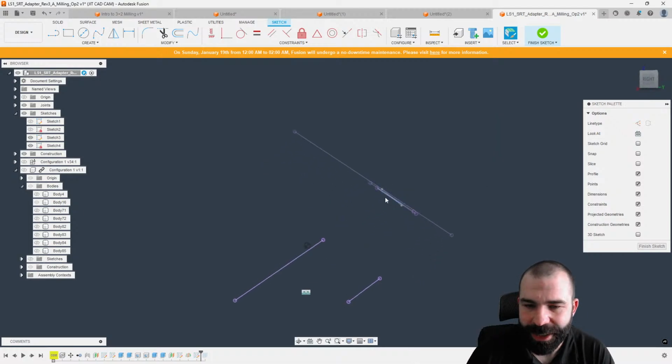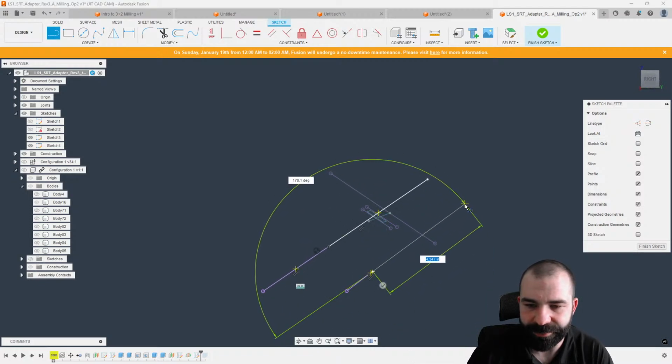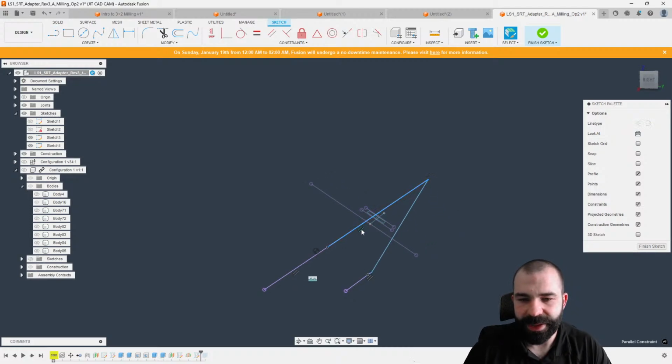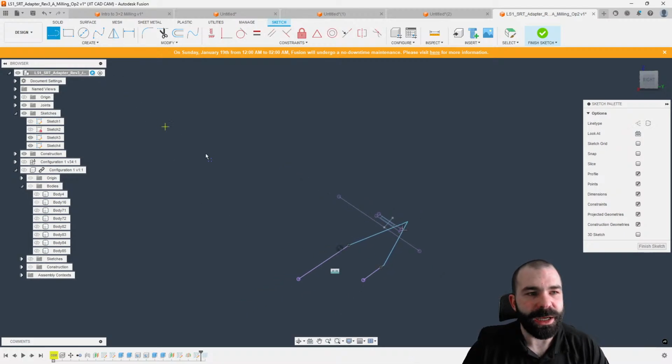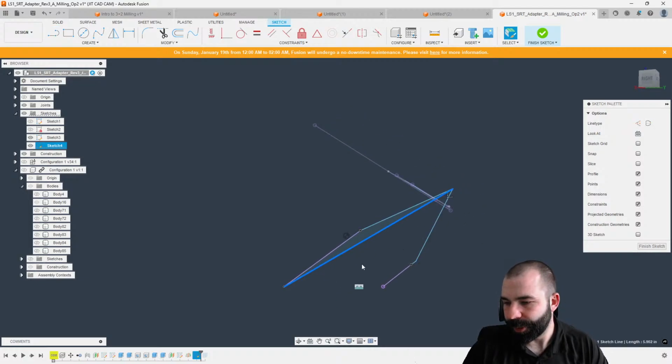Is that putting this line that I drew before basically out in space on a continuation of this line, right? So as you can see, we can run this all the way out. We could also run one from this side all the way out or wherever that flat is and basically set our point of reference so that these two technically will reach from this point. We're going to go ahead and remove that constraint. Like so. And then we know when we're machining this, right? That tool, I'm just using a line to represent it here, guys. That tool can now reach down underneath that part, right?